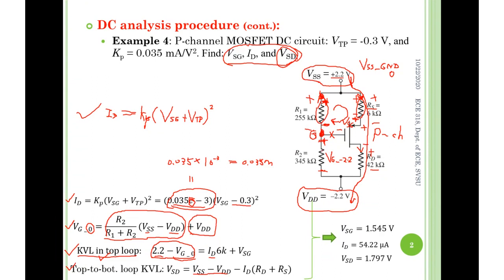The voltage potential at the terminal here is, as you know, positive 2.2 volts. Positive 2.2 volts is the voltage at this terminal with respect to the ground. Okay, this is very important. It's not mentioned that way, however by default it's just the ground. Given the power supply saying it is a positive 2.2 volts, it means nothing but the potential between that node and the ground, by default.